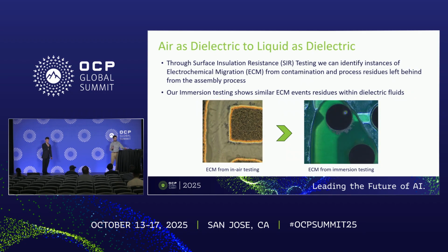So we have a deep background qualifying process residues on printed circuit board assemblies and their resultant electrochemical failures in air environments, and similar mechanisms can occur in two-phase fluids. They have the potential to extract various additives and, with boiling, deposit them under the surface of critical components in your hardware. Here you can see pictured electrochemical migration occurring in both air and in two-phase immersion